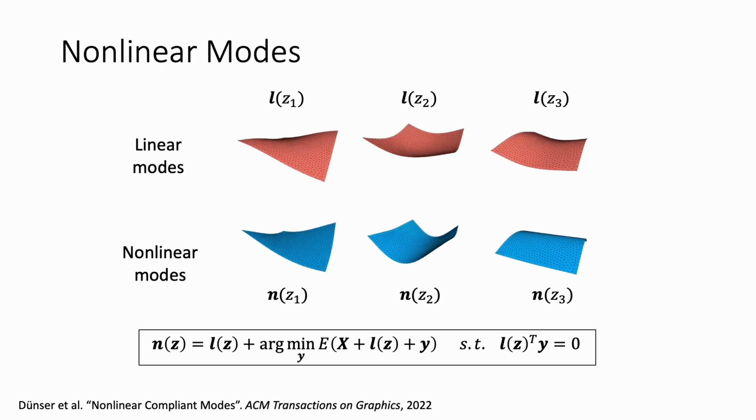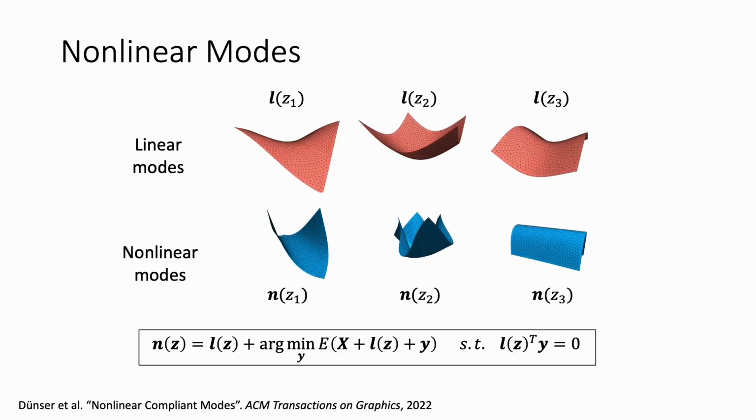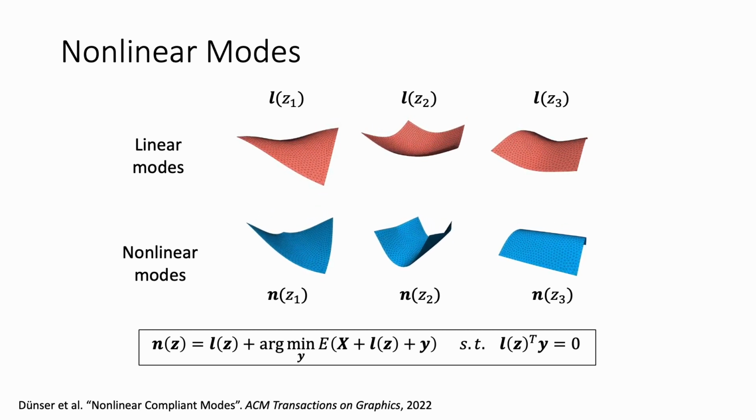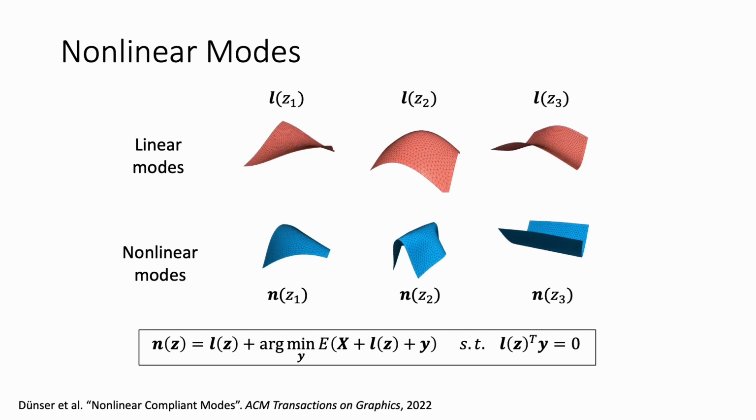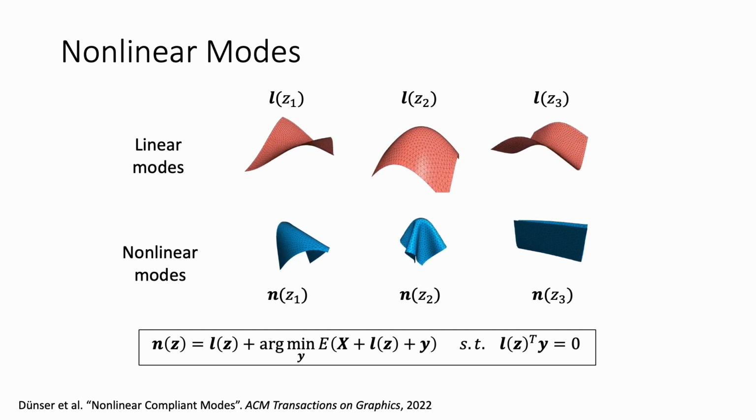We build our subspace based on nonlinear compliant modes, an extension of linear modes to the large deformation regime. Each nonlinear mode is parameterized by a modal coordinate, c, along the corresponding linear mode, L. For any modal coordinate value, the nonlinear mode shape, n, is obtained by minimizing the elastic energy in the space orthogonal to the linear mode.